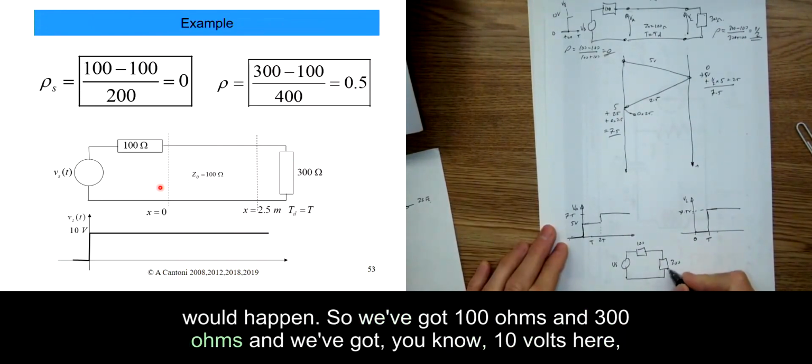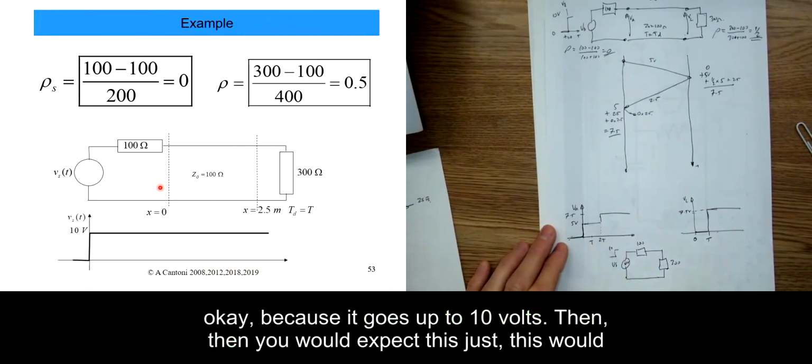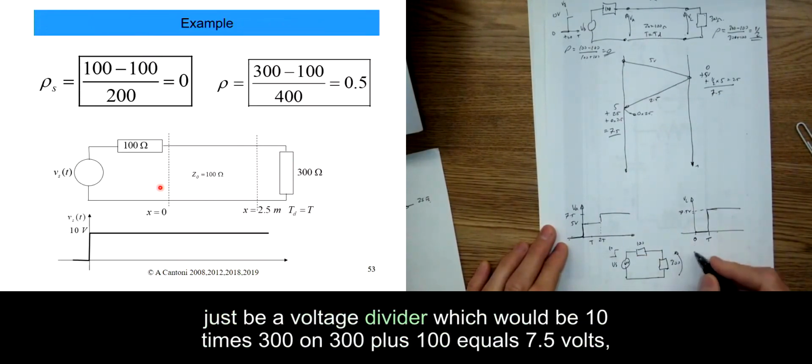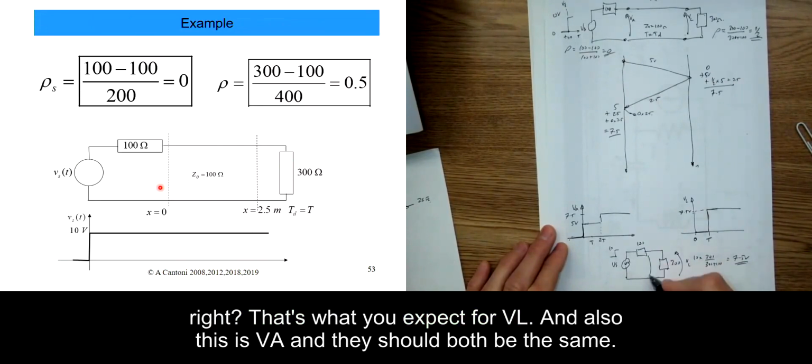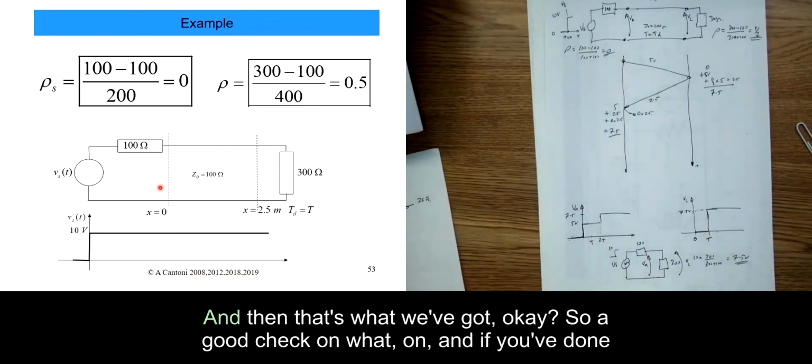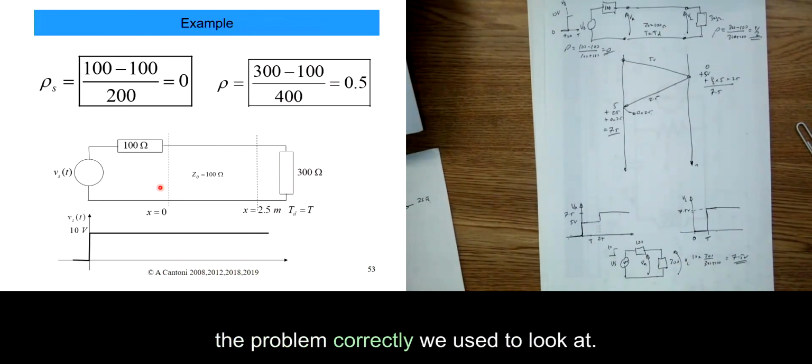So we've got 100 ohms and 300 ohms and we've got 10 volts here, okay, because it goes up to 10 volts. Then you would expect this would just be a voltage divider, which would be 10 times 300 on 300 plus 100 equals 7.5 volts, right? That's what you expect for VL. And also, this is VA, and they should both be the same. And that's what we've got, okay? So a good check, if you've done the problem correctly, is to look at